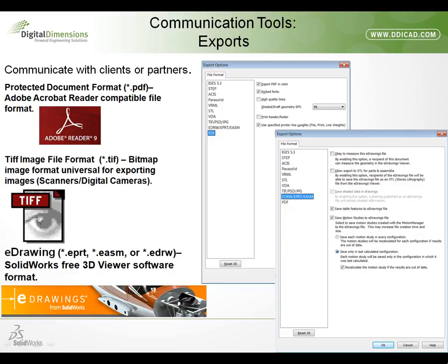Now, as we export in color, you'll notice that the shaded draft geometry DPI, when you select that option, export in color, it will convert that PDF to a raster image. A black and white PDF will come out as vector. A raster image can be described as a grid of color.